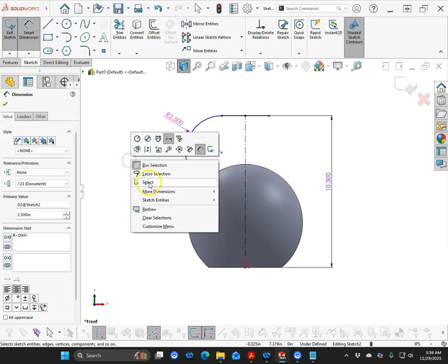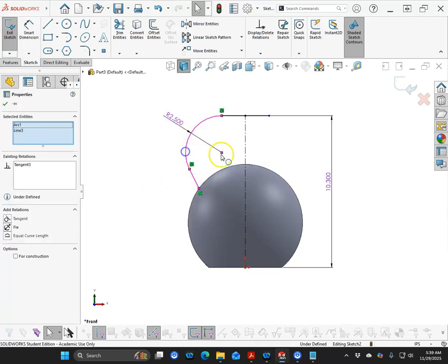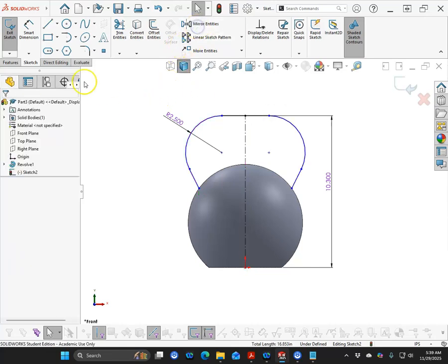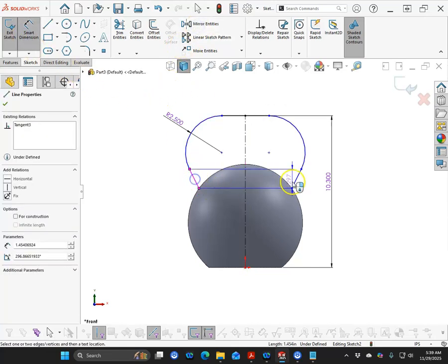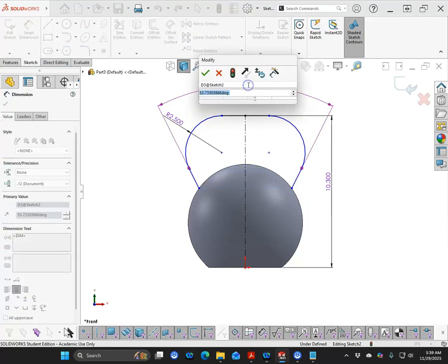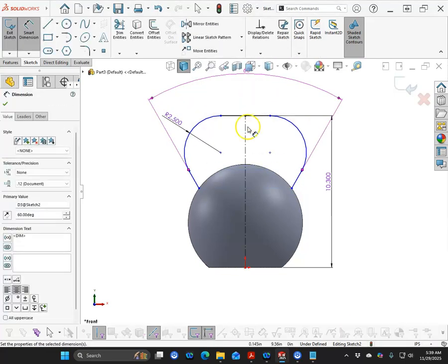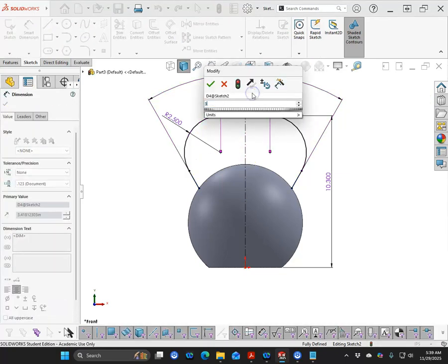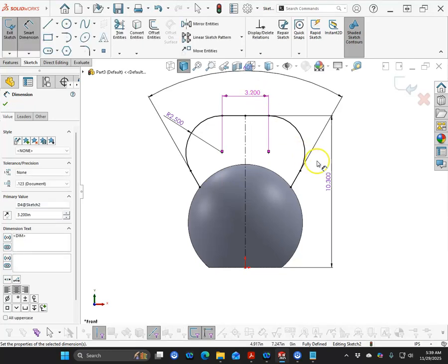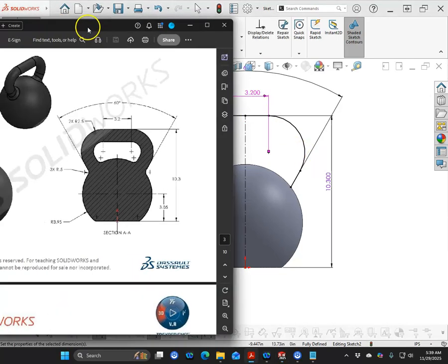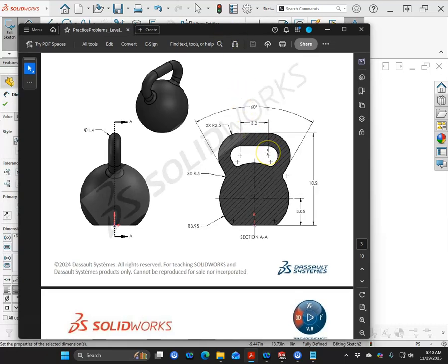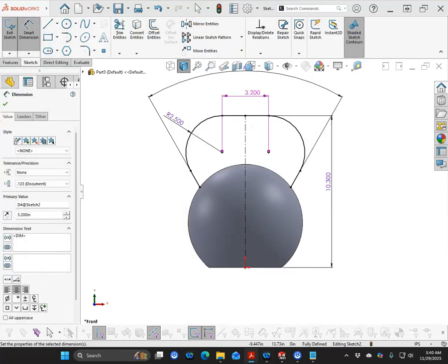And our angle then, let's go ahead and complete the mirror. And then our angle becomes 60 degrees. All right, so what am I missing? Oh, the center points between the arcs is 3.2. All right, so that gets us to fully defined. Based on the geometry, the interpretation, since that's an overall dimension, the circle is going to lie underneath. So let's go ahead and accept the sketch.